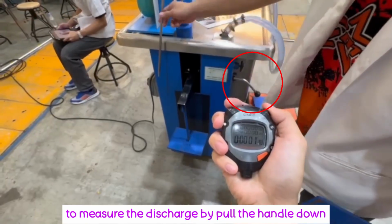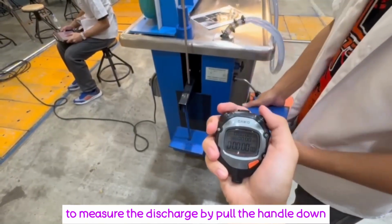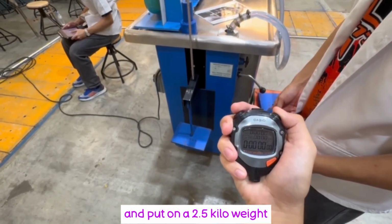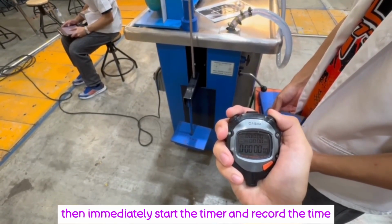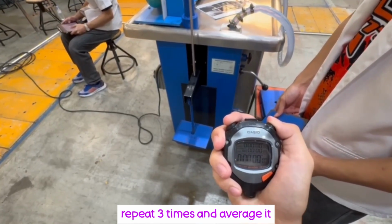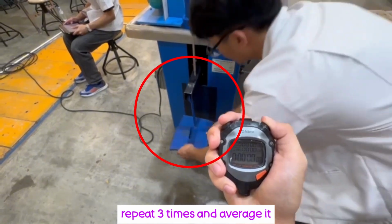To measure the discharge, pull the handle down and wait until the rod touches the arm, and pull the 2.5 kg weight. Then immediately start the timer and record the time. Repeat three times and average it.